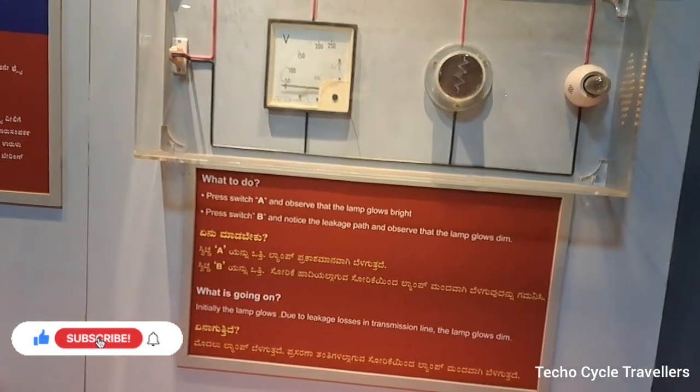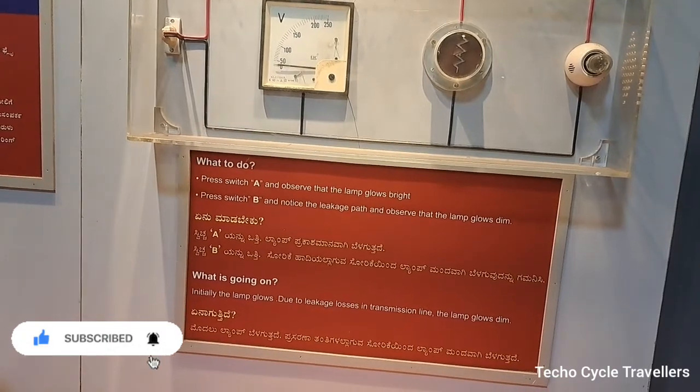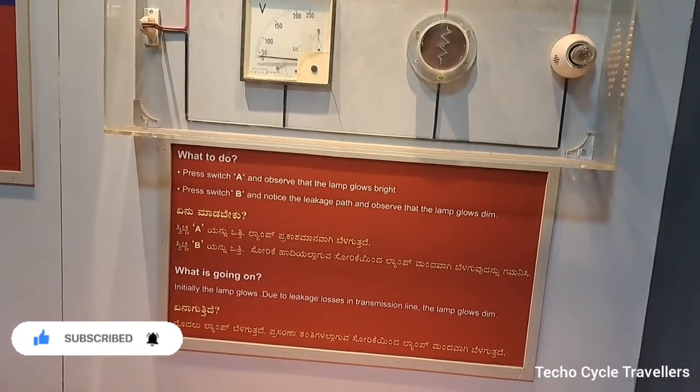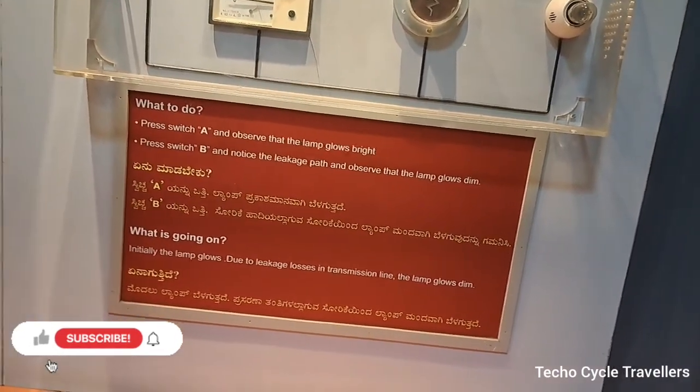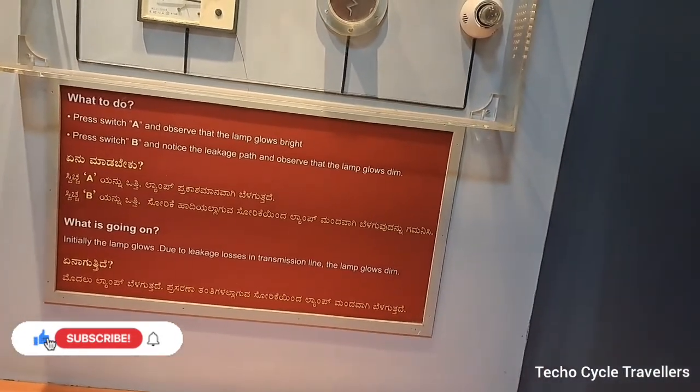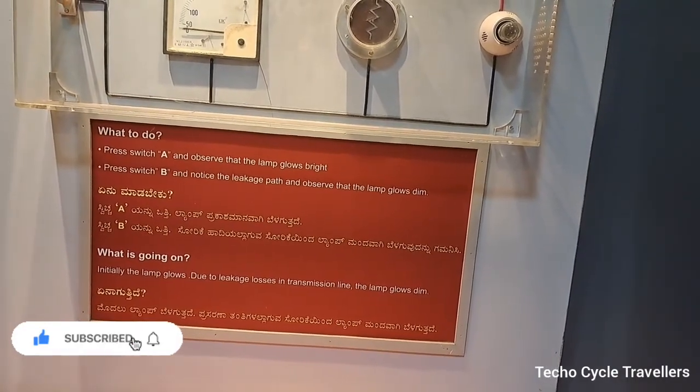Press switch A and observe that the lamp glows bright. Press switch B to open the leakage path and observe that the lamp glows dim. What's going on? Initially the lamp glows bright; due to leakage losses in the transmission line, the lamp glows dim.